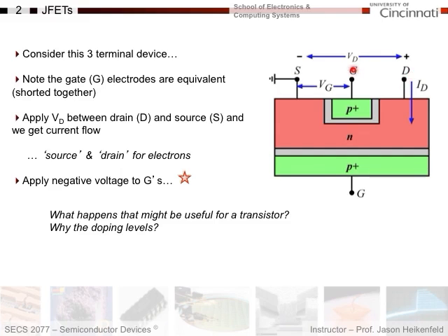I also have gate electrodes. I've got gate electrodes on both sides here, which is important. And so I'm obviously turning this device off through application of voltage here and here. And again, if I apply a voltage between the drain and the source electrodes, I will get current flow. So put positive voltage here, I get electrons going like this, which is current flow in this direction. Okay? So, let's say I've got this all set up, I've got current flow from source to drain.